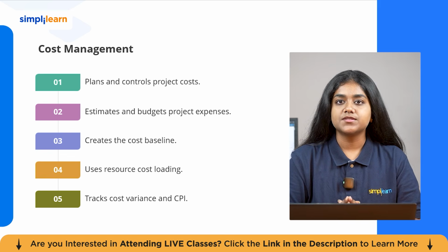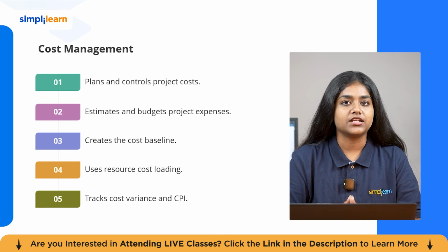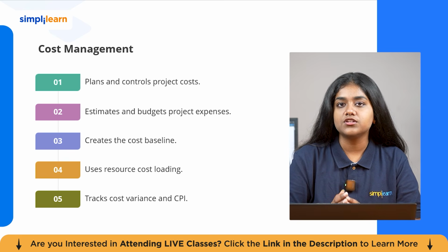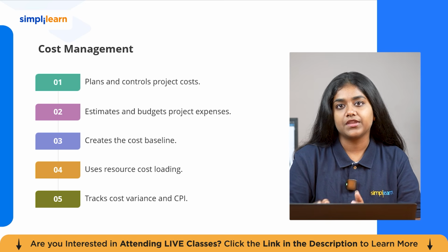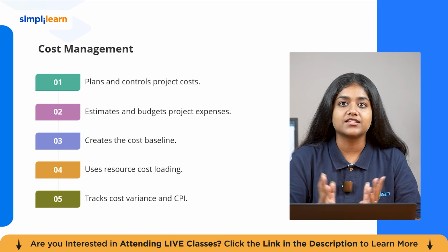In P6, cost management is built directly into the scheduling environment. Resource rates applied to activities generate budgeted cost automatically, and as actuals are recorded, cost variance and cost performance index values are calculated in real time. This integration of schedule and cost is what makes P6 the tool of choice for large capital projects.